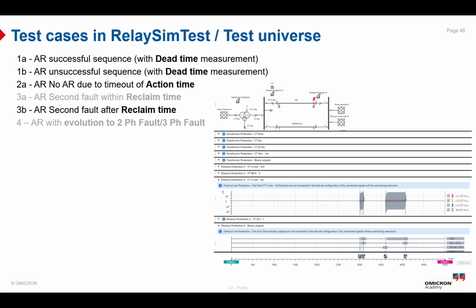And this test is valid based on the assumption that the relay reactions are consistent in every iteration. So the relay reaction in the binary traces should fall within a given time tolerance compared to the previous run. Otherwise, the shot is assigned to error and the injection will be stopped. And this can be tested with 6 test cases.